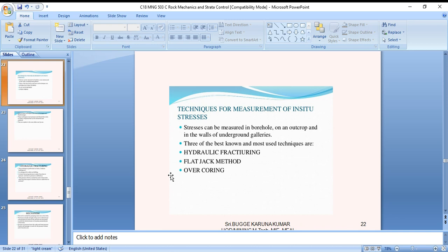Sometimes incremental instrument lengths are used. The sensitivity of the instrument generally has to meet the measurement requirements of roof-to-floor convergence. In weak, flat-bedded rock, this may amount to several inches. A convergence gauge may consist of no more than a steel scale read against an index on the rod. The sensitivity of such instruments would be about 0.01 inch, and the range several inches. The recording type of convergence gauge consists of two strings